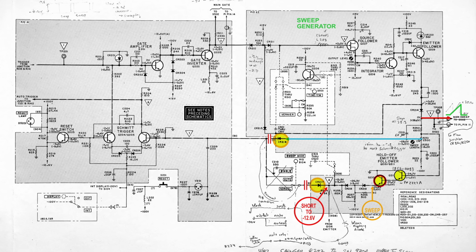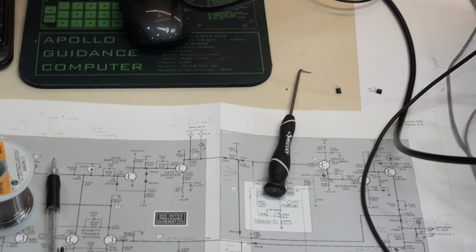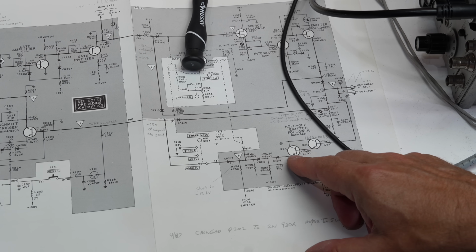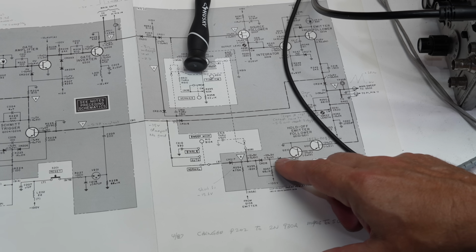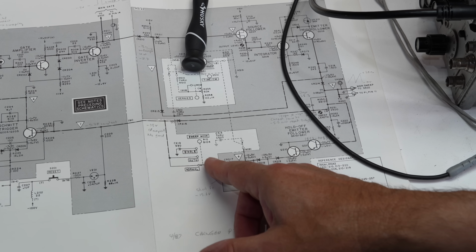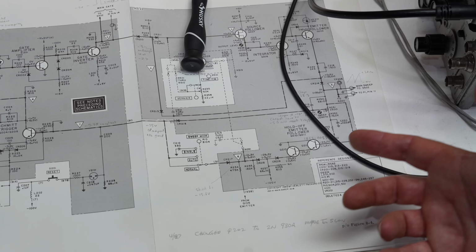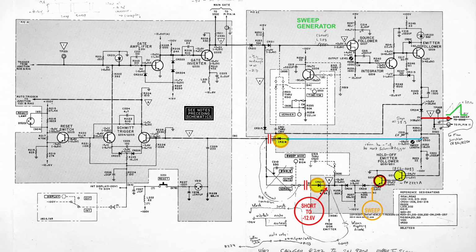We are definitely cursed. So that thing was at minus 12.6. There was no resistor to protect the poor transistor, and it blew. And I removed that CR217, so it's just isolated here. There is no 12.6 volts around. Looking for possible points of entry and having eliminated the nearby onboard components, I discovered that there is a pin hooked up to a wire under the board at port 928 that disappears in the bowels of the plug-in. I wonder if the short could come from there.